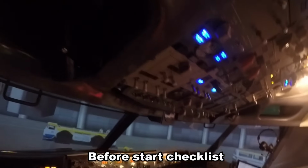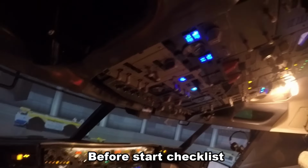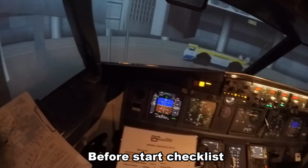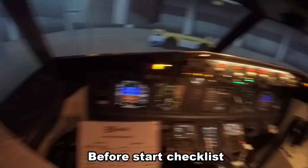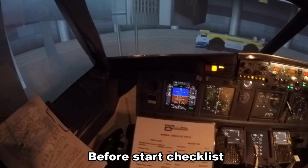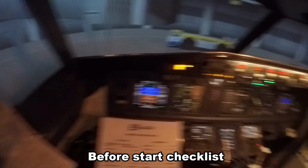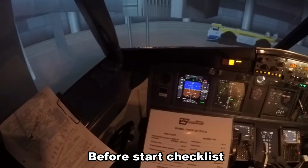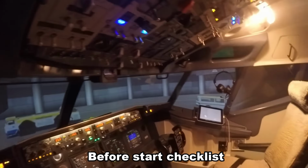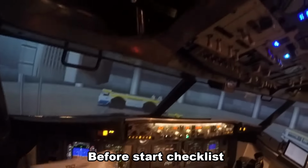Flight deck doors closed and locked. Fuel 6.5 tons, pumps are on, passenger signs are on, windows are locked, MCP V2 is 141, heading of 253, altitude of 3,000 feet, takeoff speeds V1 is 128, VR is 129, V2 is 141, CDU pre-flight is completed, rudder and aileron trim 0 and 0, taxi and takeoff briefing has been omitted, anti-collision light is on, before start checklist complete. Alright, so cockpit to ground, ready for pushback and engine start.